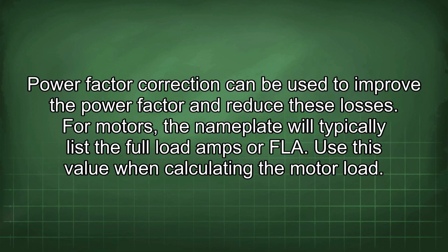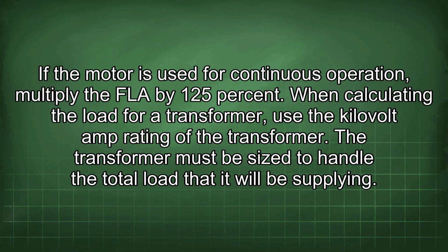For motors, the nameplate will typically list the full load amps, or FLA. Use this value when calculating the motor load. If the motor is used for continuous operation, multiply the FLA by 125%.